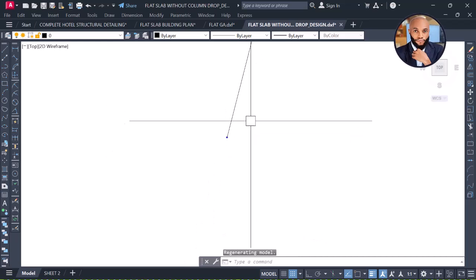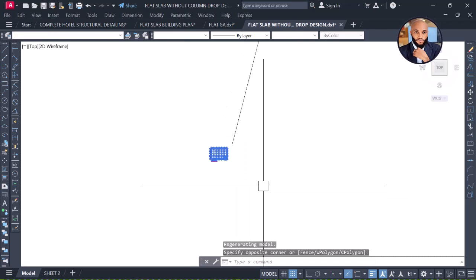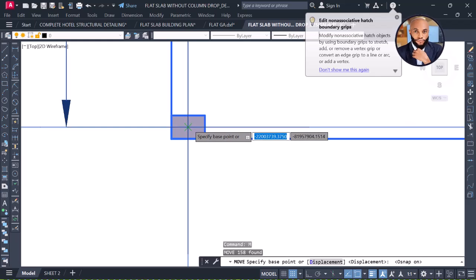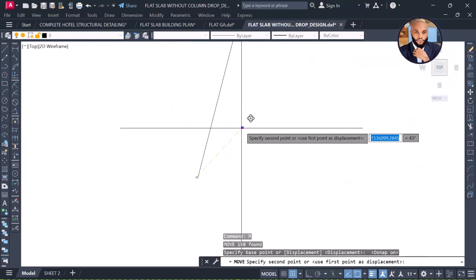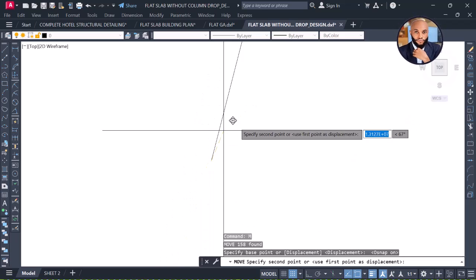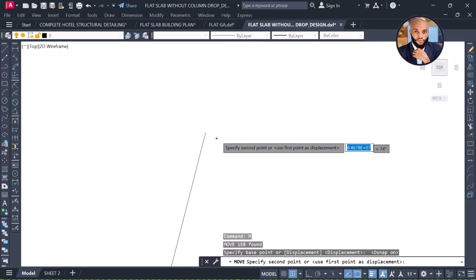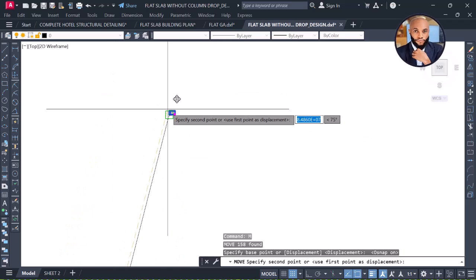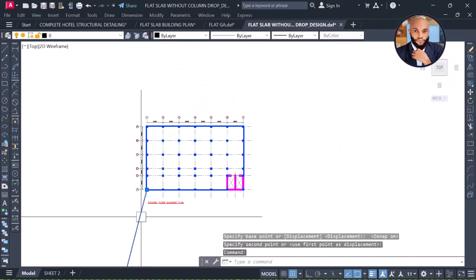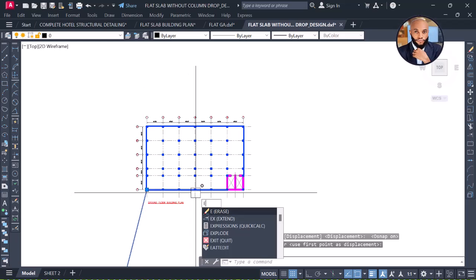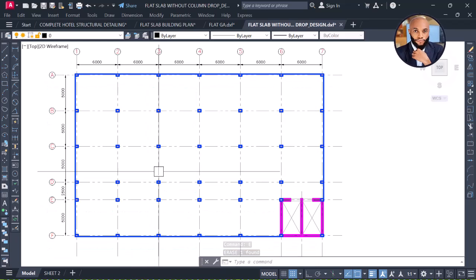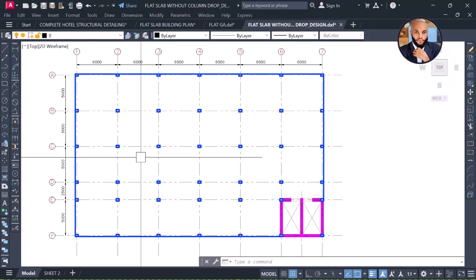So we are going to move this drawing now. Don't copy, just move from a reference point here. Let me just pick this column point here, reference point, to that end of that column. Not the beginning, but the end. The end here is where the origin is, okay. So I'll move it now to that place. By moving it now, you see that our coordinates will have to come here. So I'll keep this here, okay, and then click on this now and then enter, okay. So with this now, we have placed this drawing at origin, okay. So make sure you don't move it again, because once you move it, it will go off origin, okay.